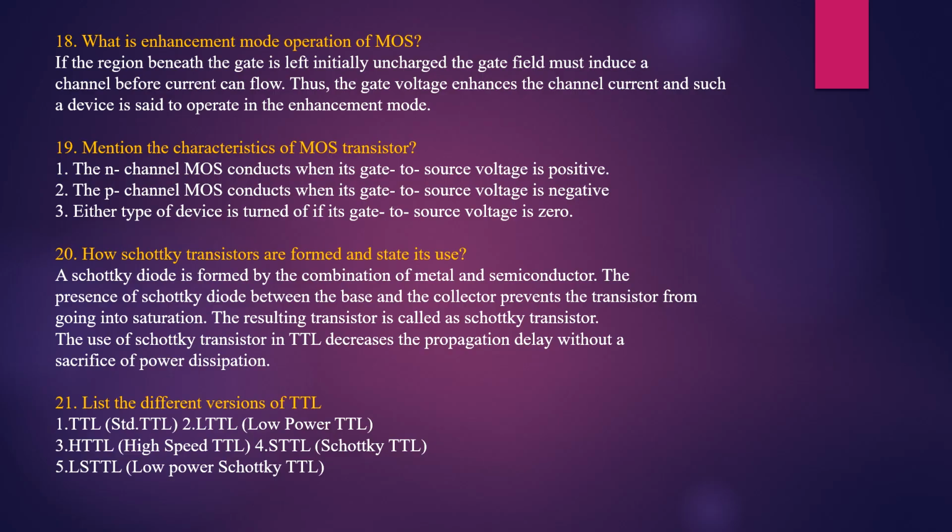If the region at the gate is left initially uncharged, the gate field must induce a channel before current can flow. Thus, the gate voltage enhances the channel current and such a device is said to operate in the enhancement mode.